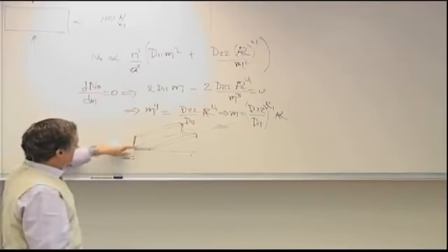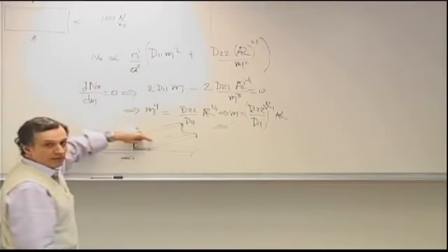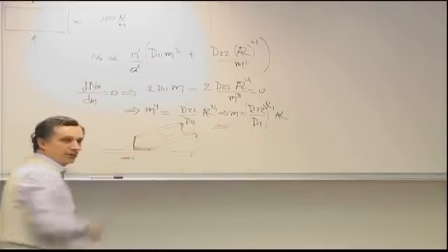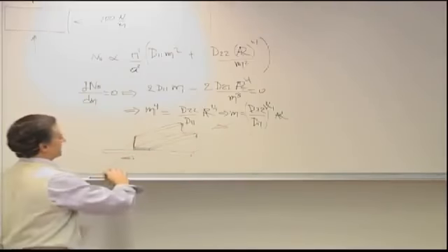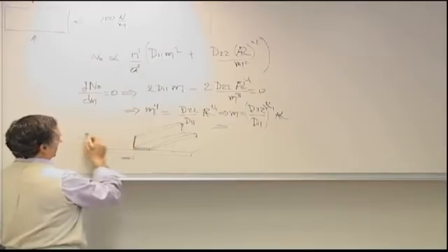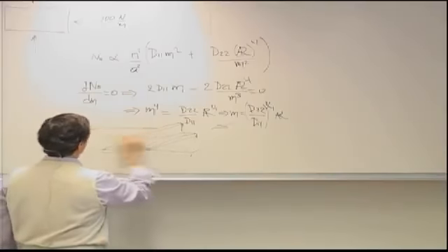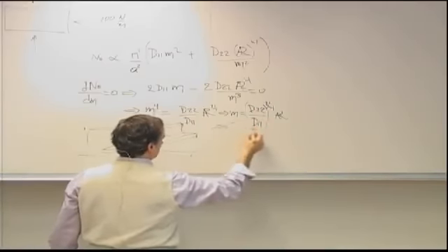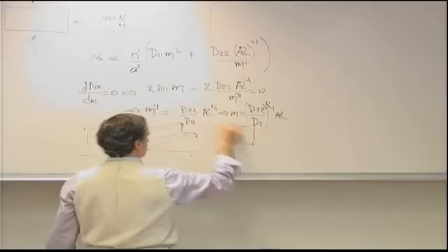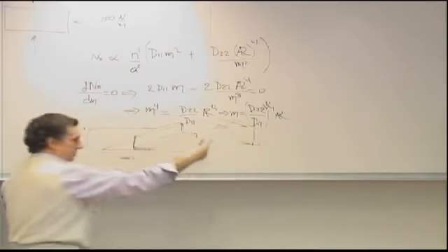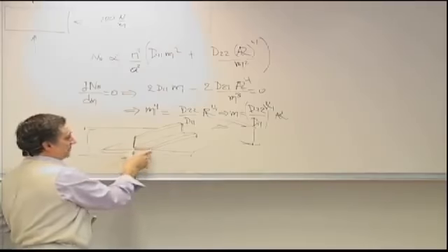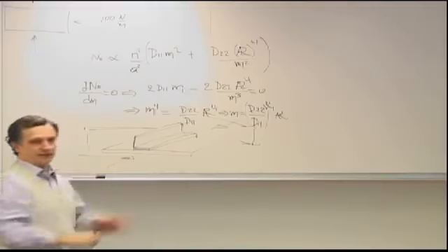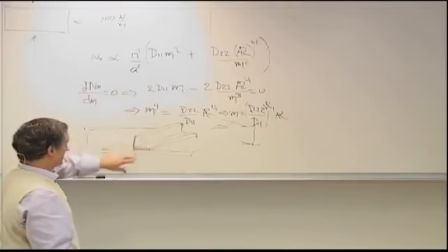And each flange, or this flange and this web, is essentially treated as simply supported at the two ends, which corresponds to some kind of frame that potentially might be sitting at each of the two ends. There might be a frame here and another frame on the other side. Let's say it's an I frame. So there is some boundary condition that's the least it could be is simply supported. In reality, it's usually more than simply supported, but rarely is it clamped.